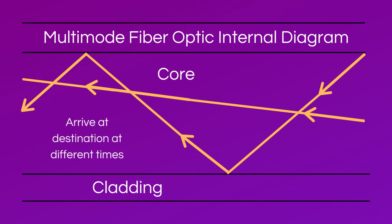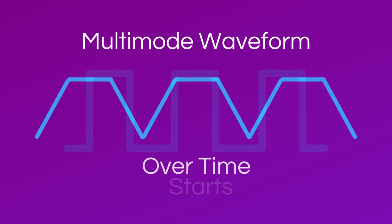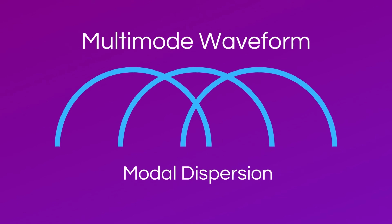When paths of light enter the fiber at different angles, they arrive at the final destination at different times because some waves travel through the cable quickly and others travel through the cable more slowly. When the light paths differ enough, the crisp square wave at the beginning of the transmission spreads and starts to look like the top half of a sine wave. Eventually, these distorted square waves overlap and start to merge. When they merge, information becomes lost. This phenomenon is called modal dispersion.